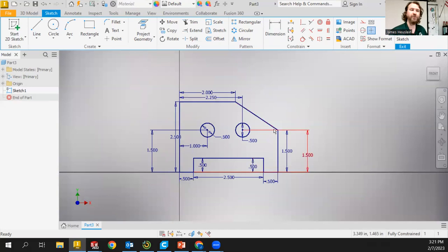We drew the front view of this drawing. We did the outside perimeter first. That's a good strategy to use. And then we did the interior components, the circles in this case, making sure that we have their diameter dimension and then their X value placement and their Y value placement to get their location correct in the part file and in the three-dimensional space that is here.